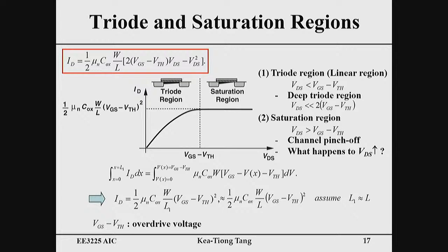So this figure is about the effect of the vertical electric field. Remember the vertical electric field? The vertical electric field is applied on the MOS device to generate the charge in the channel. And this figure is for the horizontal field. The horizontal field is the electric field generated between the drain and the source to force the carriers to flow in the channel. So these two figures are very different, and the meaning of them is very different as well.